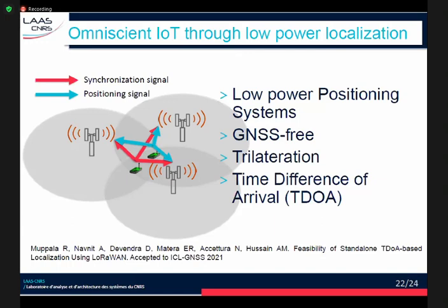The problem of that GNSS architecture is that the timing signal should be passed from one interface, the GNSS signal, to the transceiver of LoRaWAN. In doing that, we add random delays that also affect the precision of the estimate.